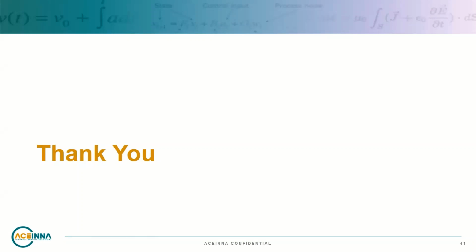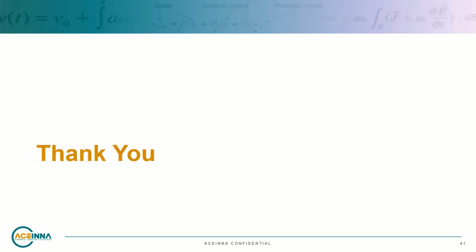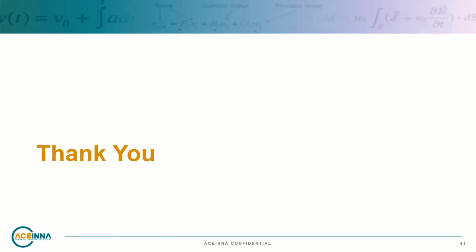This is Jamie. Let me expand on that a little bit. The evaluation kit is really meant to help speed your development of your algorithms, and it allows you to set breakpoints in the code and to quickly build and try things. Once you've completed your development of your code, we would expect you to move over to just the RI unit and load the code through the RS-232 port just by uploading the image, using the integrated bootloader, or, coming in the not too distant future, via the CAN bus.